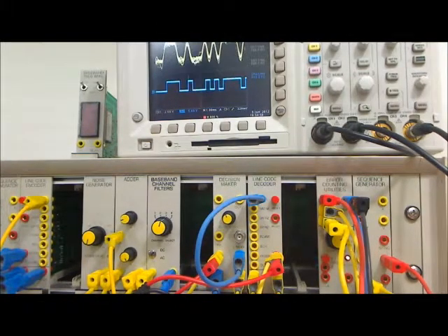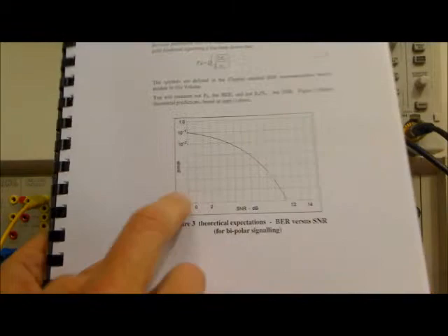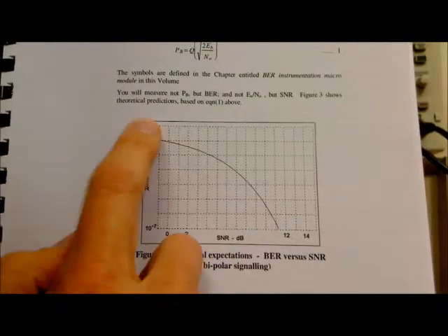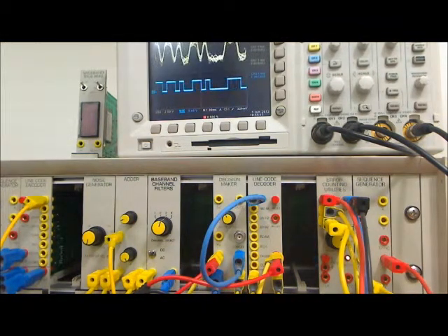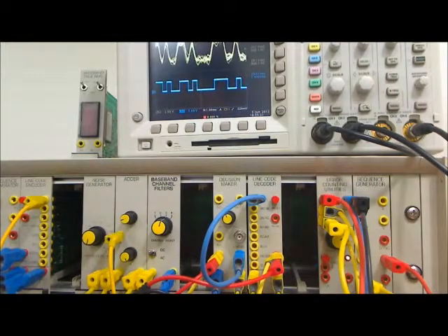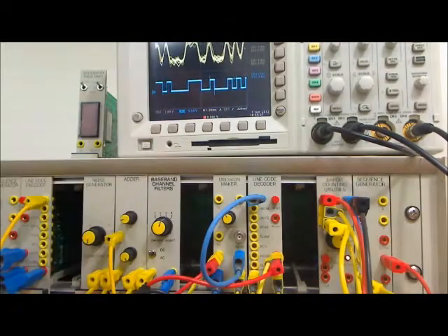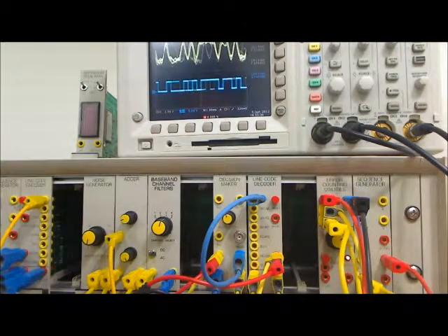So now, if you have that bit error rate and the signal to noise level, the student is now able to plot the bit error rate curves versus signal to noise in dB for the system. And using this system, the student is able to compare the performance of this real system with the theoretical expectations. This same technique can be applied to all the other modulation schemes we have in TIMS: BPSK, QPSK, spread spectrum, and all the other line-coded systems.